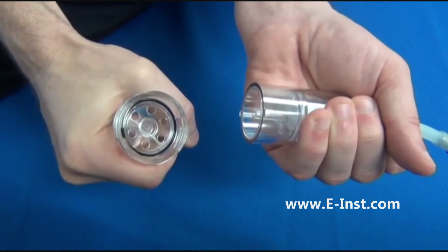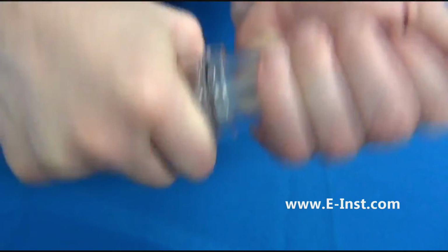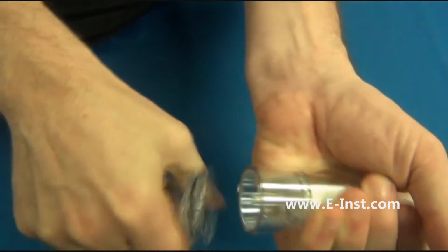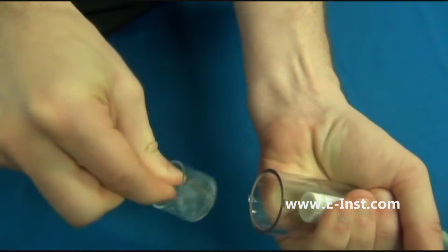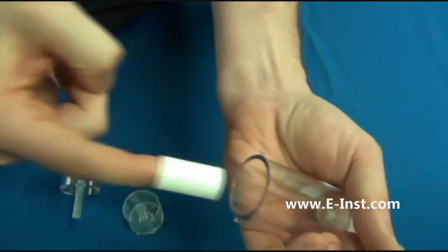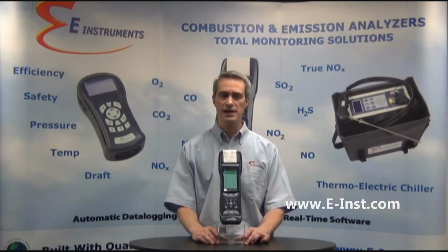Inspect the external water trap. If there is any presence at all of condensation, empty it before each use. Next, take a look at the filter cartridge in the upper chamber of the water trap. Unlike some other analyzers, E-Instruments filter gets dirty from the outside in. This allows you to easily see any dirt buildup without having to take the water trap assembly apart and look